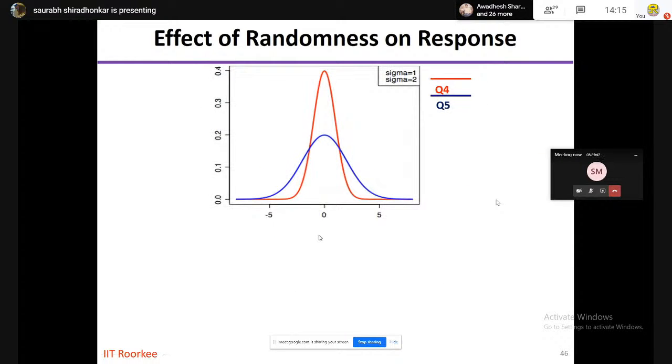Now, if you again compare the distribution which you have obtained from question number 4 and question number 5, question number 4 is for one ground motion, and question number 5 is for large ground motion. Then again, the mean value could remain same, but the standard deviation will be a lot larger in question number 5, and that's mainly because the ground motion that you have will have various characteristics, and it can impose a large variation into the deflection.